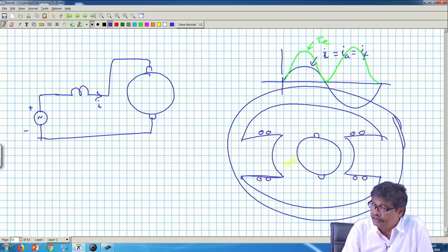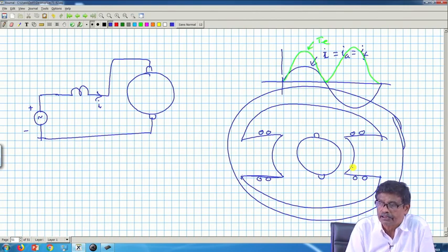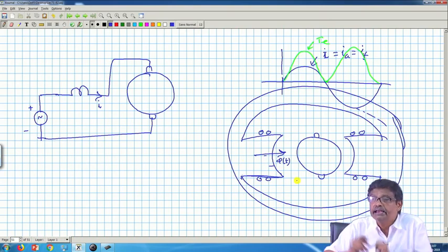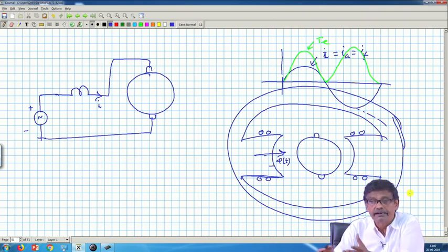But now these are the field coils. I have planned that the armature and field coils will be in series, and I plan to excite it from AC supply. The moment you do, the flux here will become a function of time. Therefore, this flux will be flowing like this through the yokes, and if it is solid iron, eddy current loss and hysteresis loss will take place in the stator iron structure as well.